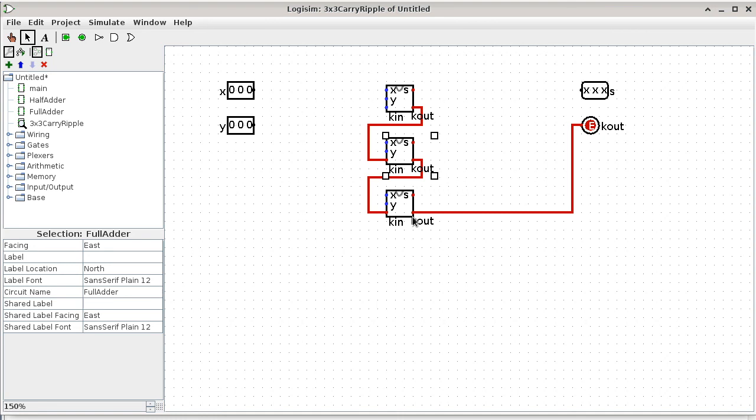Okay? All right. So now we need to figure out, how do we get this to here? And it goes like, uh-oh, doesn't work, because the pin has 3 bits, but the X bit of the full adder is only a 1-bit input. Okay, so that's not going to work. All right, well, if it doesn't work, we undo. So what we need to do now is to split a multi-bit thing into individual bits. Can anyone guess what type of thing we need to get it done?